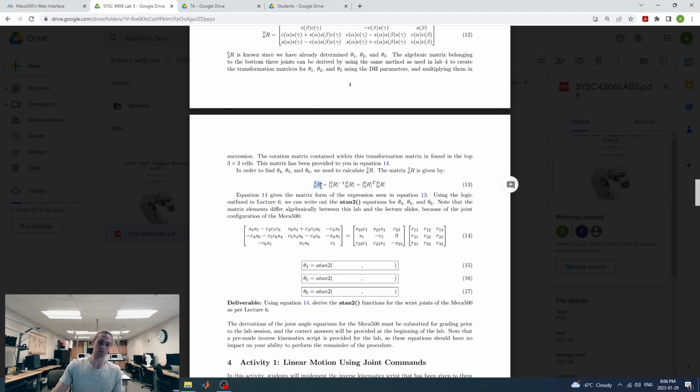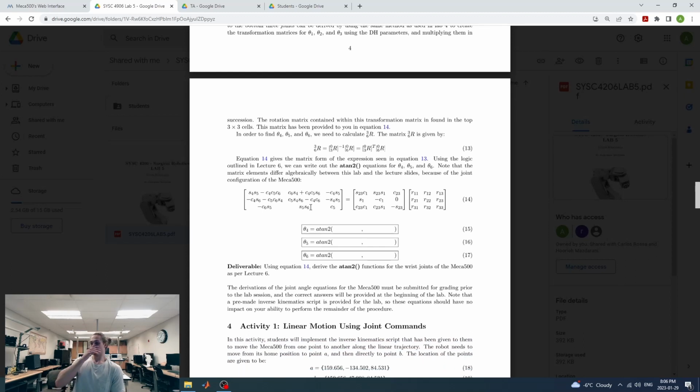We haven't solved for any of those joint angles yet, and it's equal to either the inverse or the transpose of R03 multiplied by R06. So when you look at the result of these matrices that we already know, you could probably just use arcsine or arccosine to determine the joint angles, and you'll have to divide some things. But that's pretty susceptible to dividing by 0 if you have like 90 degrees somewhere in one of the matrix elements. So in robotics, it's favorable to use the atan2 function because this also determines which quadrant your joint might lie in.